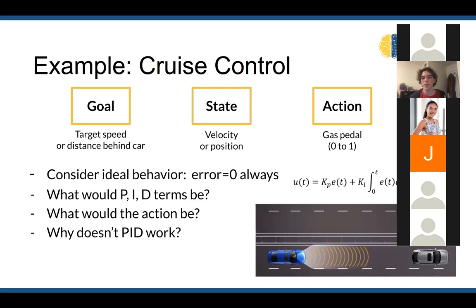Optimal behavior is not stable under PID in a system like this. In a system where we're trying to reach a finish line, removing your foot from the gas is perfect if you're at the goal. That works, but PID doesn't always work for every system, or it's not very natural to pick. And we can observe this mathematically